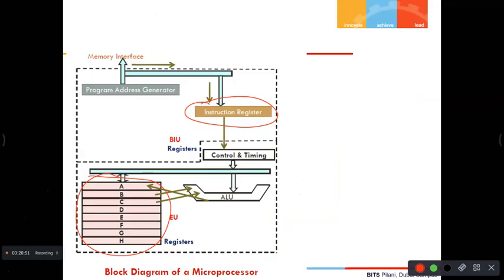See here, these registers are named register A, register B, register C, D, E, F, G, like that. Depending on the particular microprocessor, for example from Intel or from Motorola, they have different names. We are going by the Intel microprocessor, which is called the 8086 processor. But in general, registers are named by alphabets, sometimes by their own name. So what you need to understand is that your microprocessor consists of a set of registers, and these are the same registers which you studied in your digital design, nothing else.